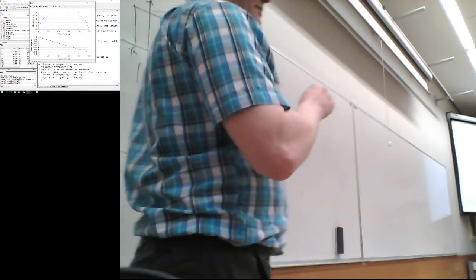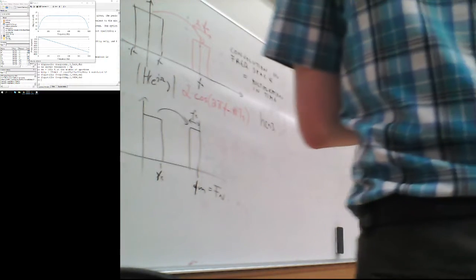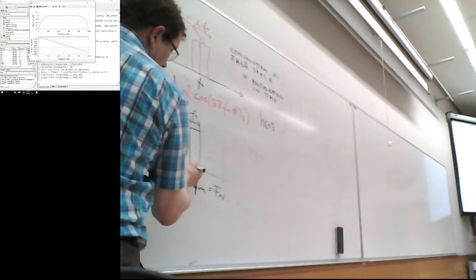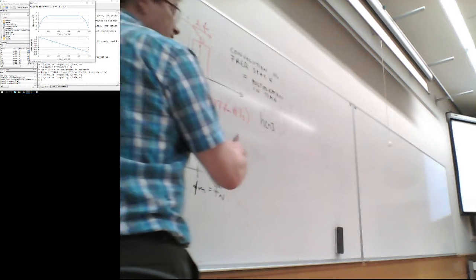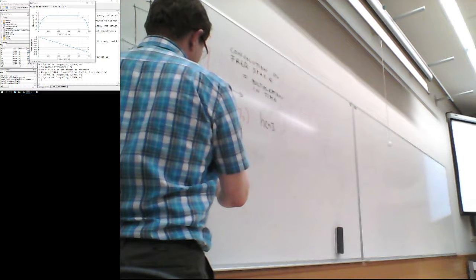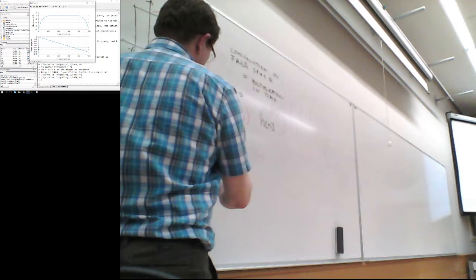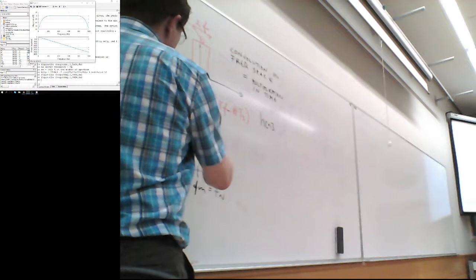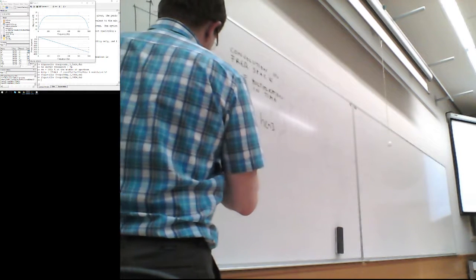Okay, there is a trick in the exercise. When you're doing the exercise, I'm actually defining the cutoff frequency of the high pass filter somewhere here. So first you need to think of what is the bandwidth of this high pass filter, so that you will design the low pass filter correspondingly.